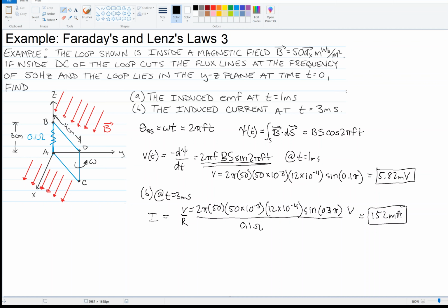What we need, though, is something to turn that loop. You could have a crank, like a human could be cranking this thing around, which would generate AC power. It could be energy harvested from gasoline that pushes this coil in the magnetic field, or you could boil water, and the steam would push the blades of a turbine, and the turbine would spin, and then you have, again, this rotational movement in a magnetic field, and that would also generate AC power.